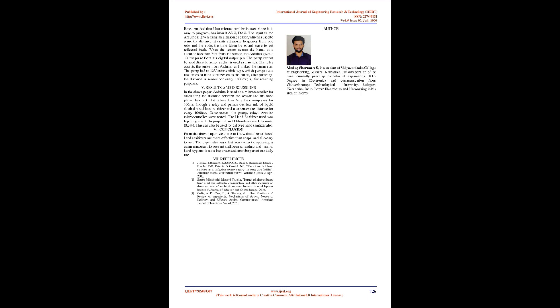Results and discussions: in the above paper, Arduino is used as a microcontroller for calculating the distance between the sensor and the hand placed below it. If it is less than 7 centimeters, then the pump runs for 100 milliseconds through a relay and pumps out a few ml of liquid alcohol-based hand sanitizer, and also senses the distance every 1000 milliseconds.